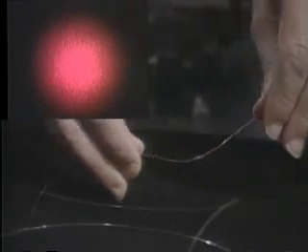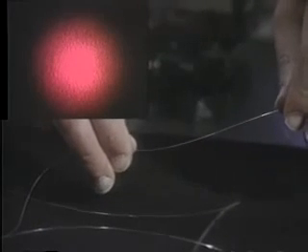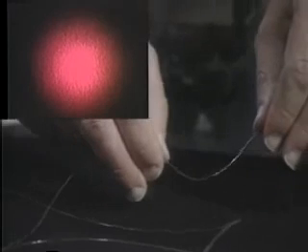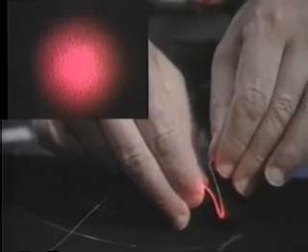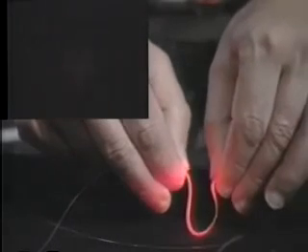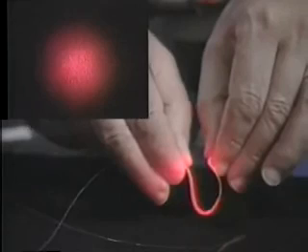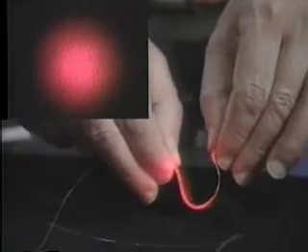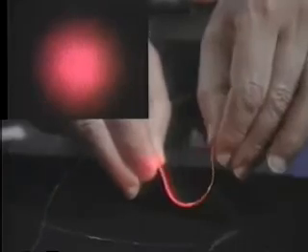So the illustration here shows that if you leave the fiber alone without sharp bends, everything is fine. If you put in a bend, then you can kick out a lot of light, and not much will be transmitted. So you have to be careful. You don't put it too tight a bend, otherwise your fiber is brittle and you break the fiber. So you have to be careful how you do this.